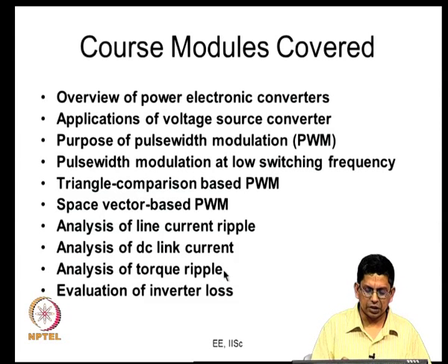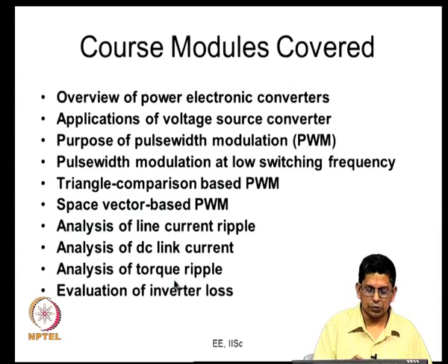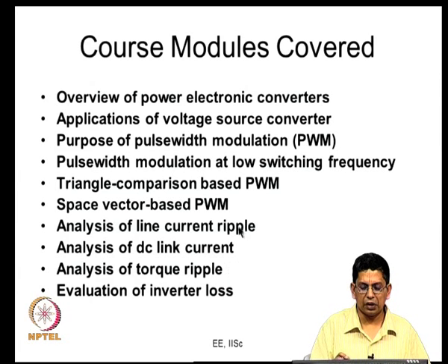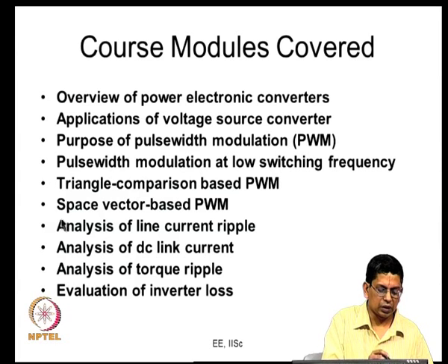In another lecture in the same module we looked at the high frequency PWM and tried to analyze that. There once again we looked at the error between the applied voltage vector and the reference voltage vector, very similar to what we did in the case of line current ripple. So, those three modules were actually on analysis.